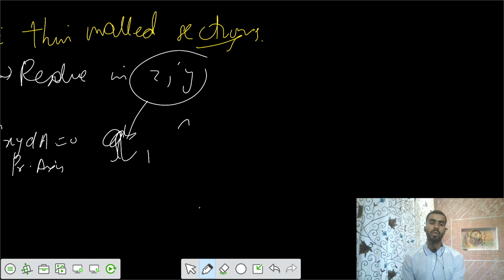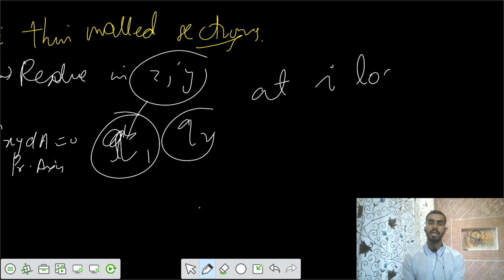You get the values of shear flow at any location i where you want to find shear stresses. You get the shear flow Qi1 at that location, and similarly Qi2, the shear flow in the second direction at the ith location.